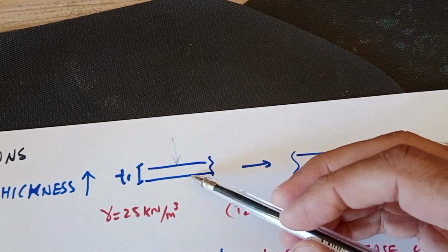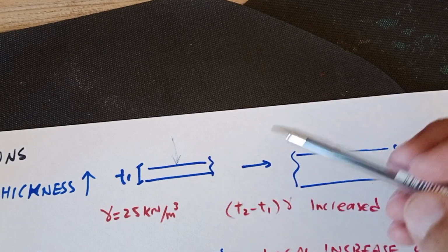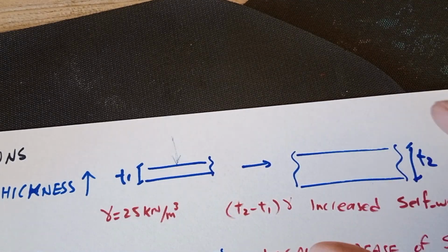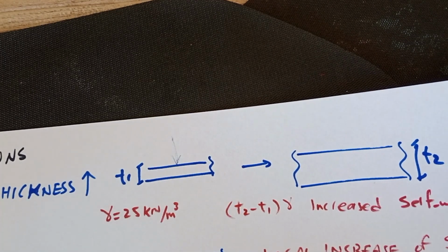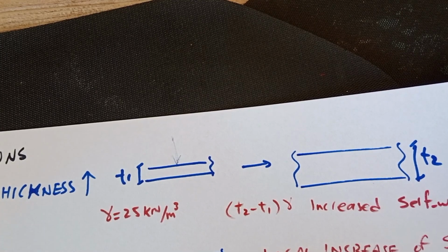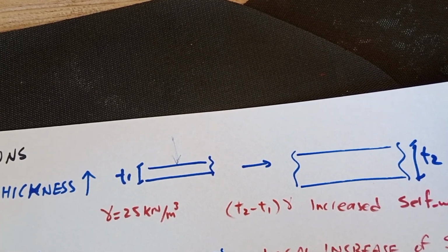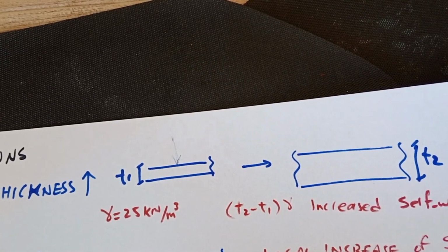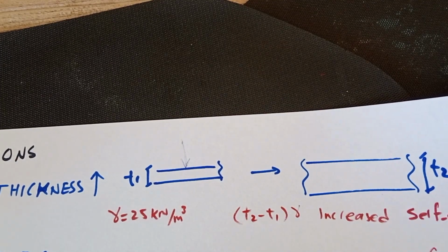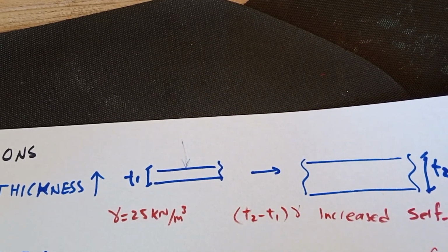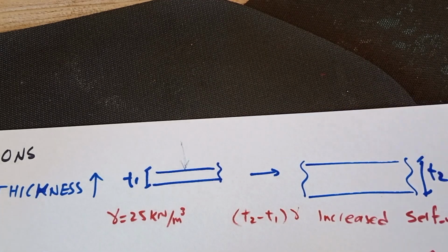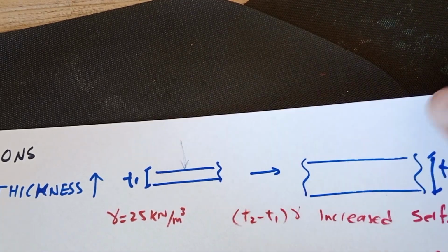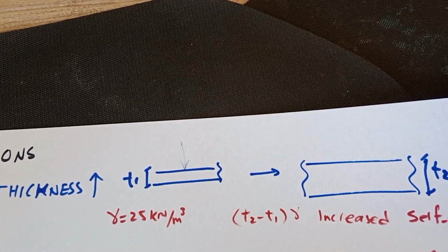The easiest way is to increase the slab thickness, because a thicker slab means thicker section depth, and thicker section depth means better deflection capacity, better inertia, or stiffness capacity. It will decrease the deflection and help to keep it within the deflection limit. It is also very helpful for punching shear and shear transfer.